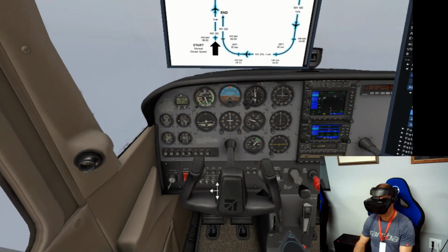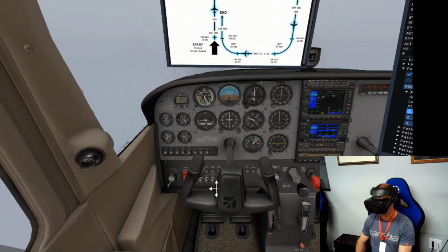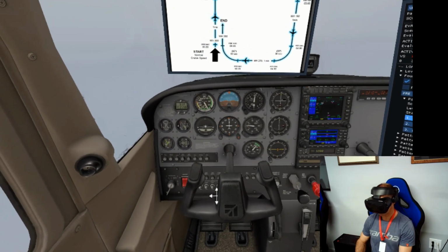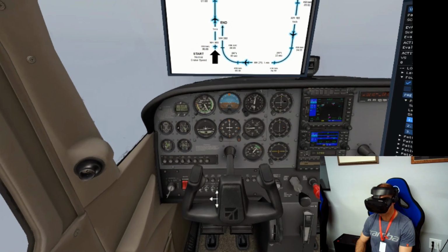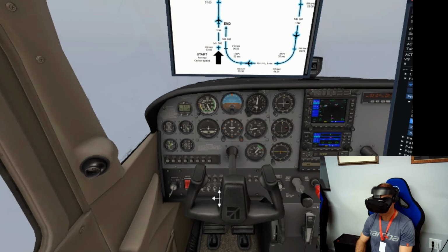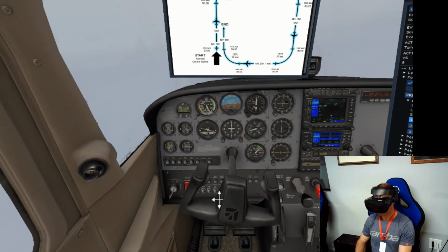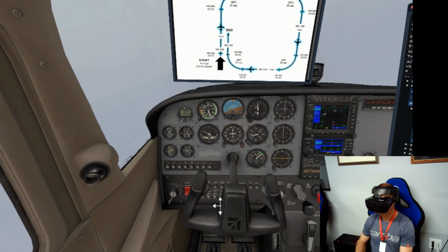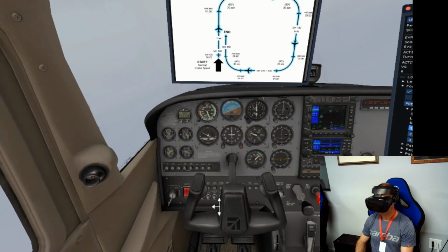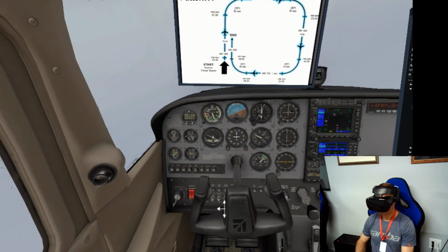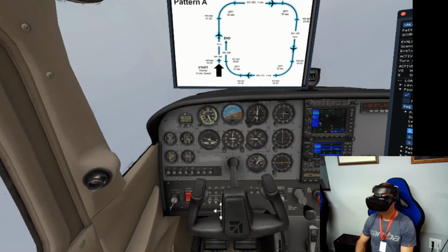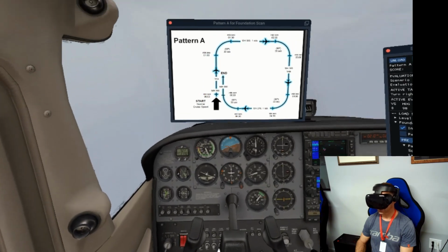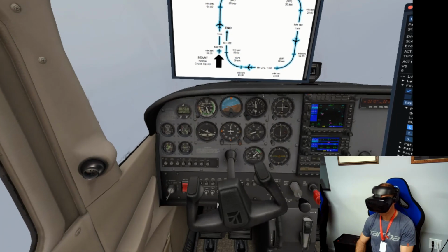So I'm primarily focusing on the artificial horizon there and just ever so often glancing at the other instruments. Primarily it is the AI though that I'm putting most of my effort. Now, start a right turn to 90 degrees for 30 seconds. And as I roll, I'm adding a little bit of back pressure here. You do lose a little bit of lift when you're in a bank turn. And I have a standard rate bank turn here, so that should give me the 30 seconds.